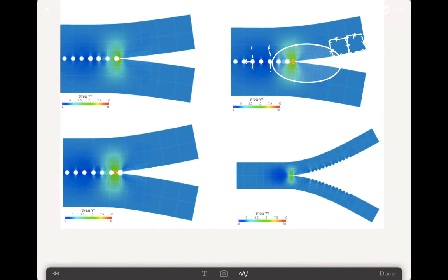And if you look, I don't think you can see very closely into this, but the maximum number of elements that one of the larger ones has been divided into along the length is more than about 20 during adaptive refinement. Therefore, we are able to move from one node to the next node without causing any computational failure or very large oscillations in the results. However, it took a very long time to run such an analysis.